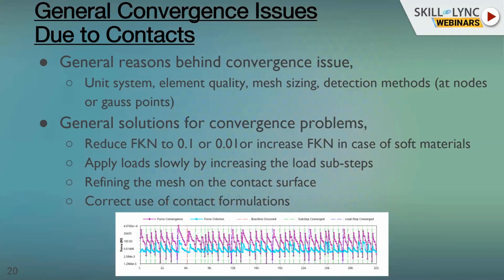You might have come across this kind of scenario, like the problem is solved, I have applied the force, but contact itself is not detecting. Two surfaces are penetrating within each other. The force transfer is not happening. That is because the applied load step is high. We need to increase the load slowly in small increments. So that is the kind of technique you can follow.